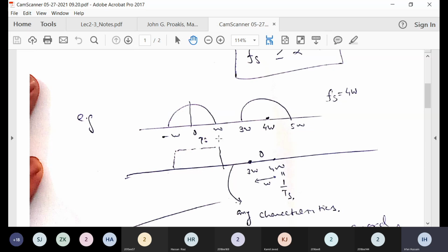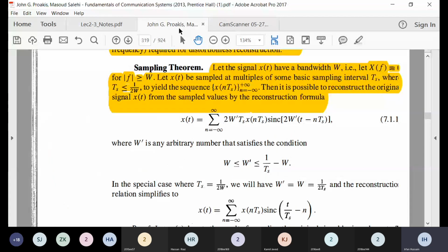This is the actual intuition, and it can be understood conceptually only in the frequency domain. You pass your replicated spectra, because of the sampled signal, through a low pass filter in such a way that you get back the original signal. Is everyone understanding? Has everyone understood the thumb rule with respect to the sampling theorem?